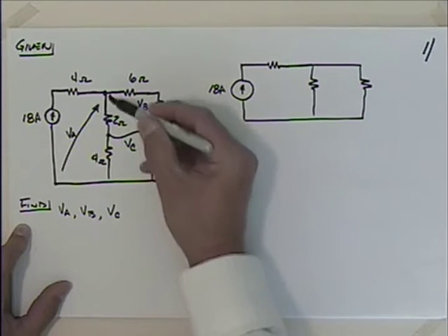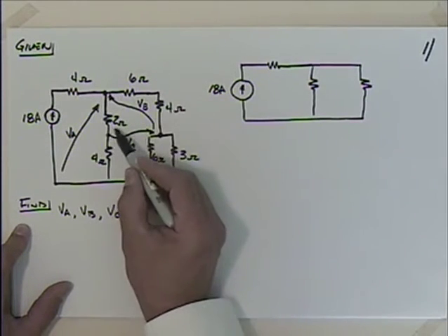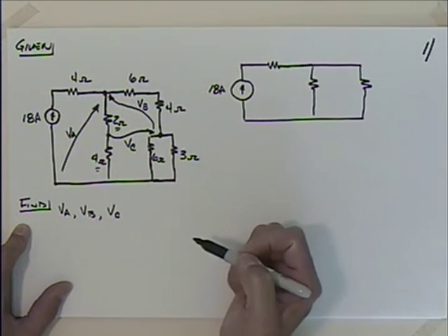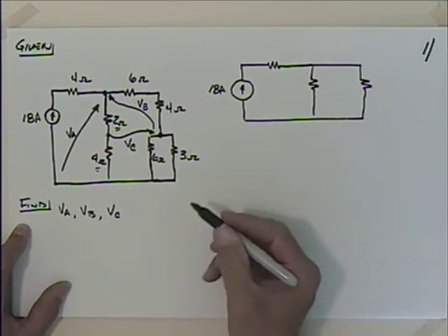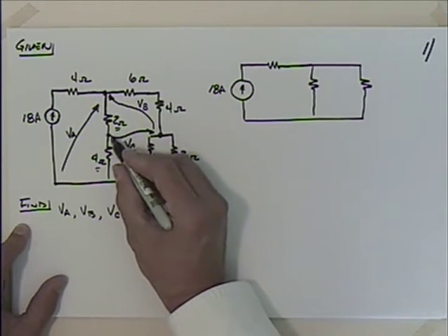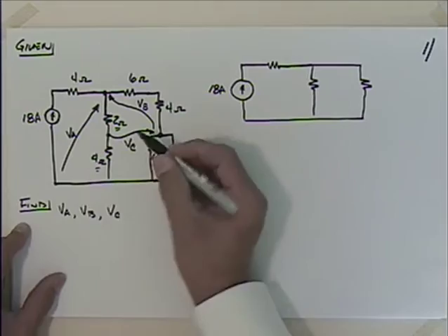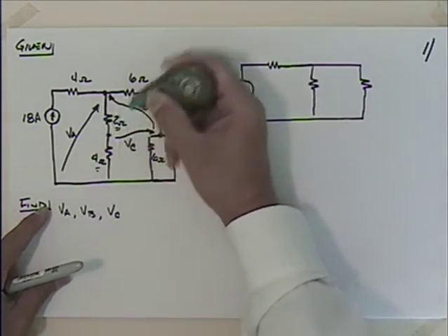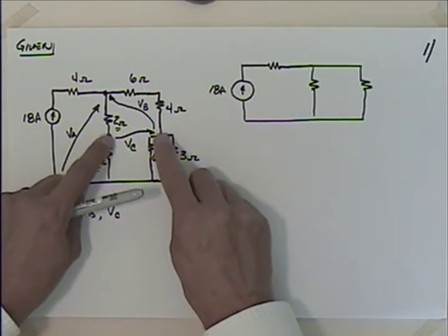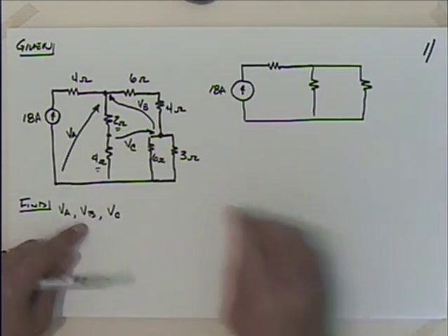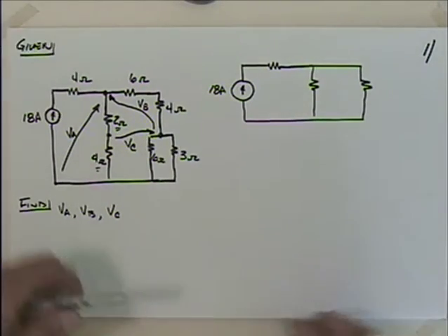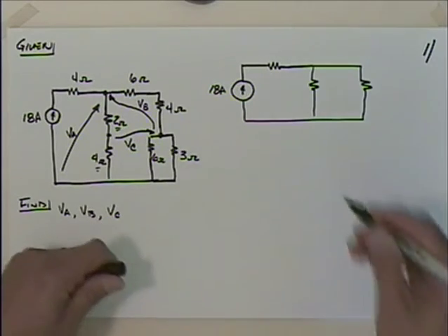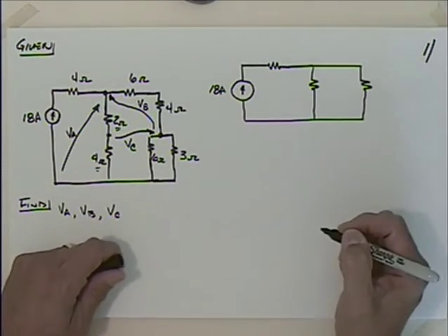Well, if we look at the relationship of this 2 ohm resistor here and that 4 ohm resistor there, pretty obvious those are in series. This VC is just a measurement. There's not an actual path. Maybe I need to be a little more careful in my drawing. This is not touching this point here. We would just be measuring the voltage across there. There's not a path for it to flow through. Hopefully there would not be that much going through our voltmeter, and we'll actually look at a problem that deals with that in a little bit.